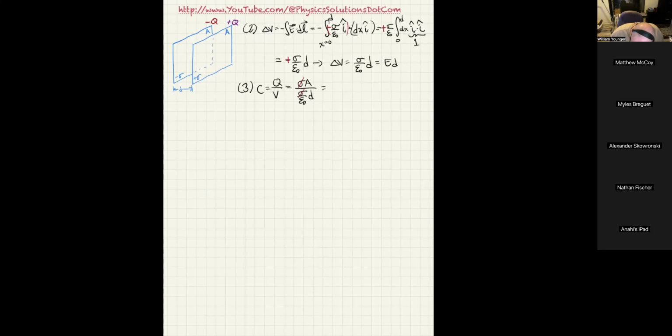So with that in mind, you can now see that the epsilon 0 comes up top, and the answer is going to be epsilon 0 times A over D. And that means the capacitance of a parallel plate capacitor is epsilon 0 A over D. And that's the derivation that you are supposed to be able to do. Anybody have any questions on that one? Okay. Well, we've done that now. We did a derivation of the capacitance for a parallel plate capacitor.